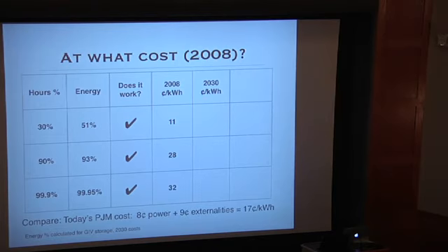So the distribution doesn't change. All we need to do is upgrade the high voltage system. Busbar would be at the plant. We need to get to the substation. So we didn't include that here, and I'm just warning you if you want to be more careful. I wish I could have modeled transmission. Hugo and Warren are going to do that. We're going to have some actual data, and we'll see if it blows these numbers out of the water. But this does not include transmission. My guidance is add 20% for that. You don't have to believe me.